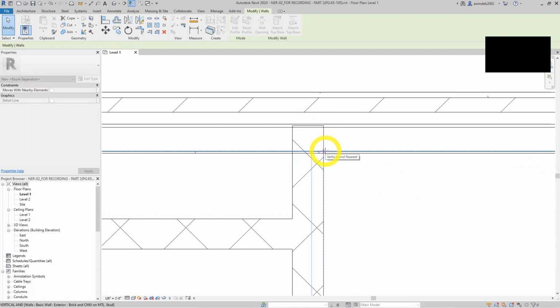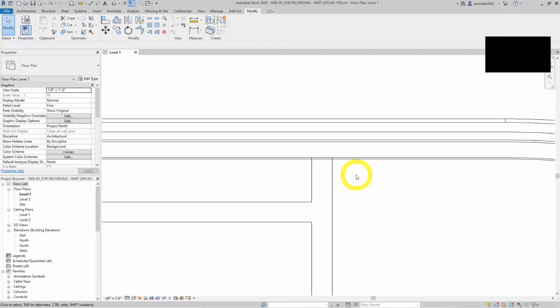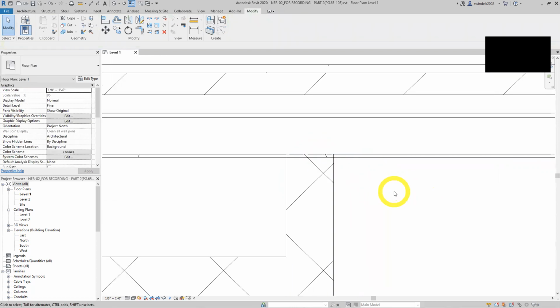We're going to go back to this point. Bam, right there. Interior of the sheetrock. Left click somewhere out in space. It should look like this. Okay. And we're going to go to the graphics panel of the View tab to cut the profile now. So the View tab is up here.